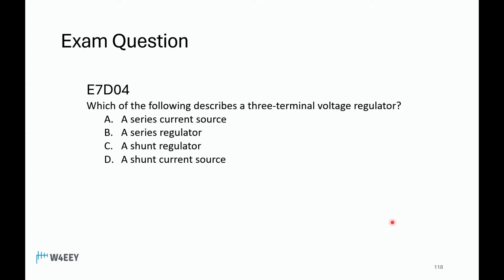Bravo. It is Bravo. It's a series regulator, but it would be set for a fairly low amount of current output. A little three-terminal small transistor-sized package wouldn't be able to handle a transceiver.